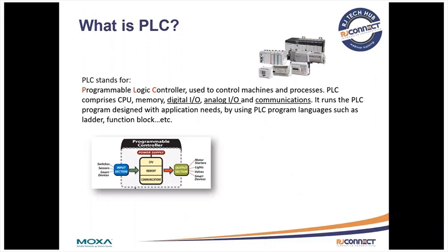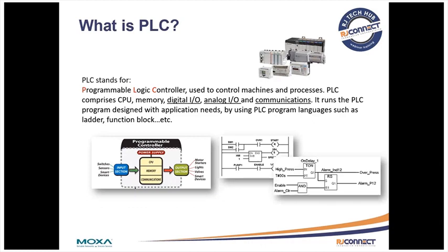Now, what is a PLC? So a PLC is a programmable logic controller. This is used to control machines and processes. The PLC comprises a CPU, memory, digital inputs and outputs, as well as analog inputs and outputs. But it also gives us the ability to communicate with our SCADA systems. It runs the PLC program designed for the application needs by using a PLC programming language such as ladder logic, function block diagrams, and STL or structured text language.